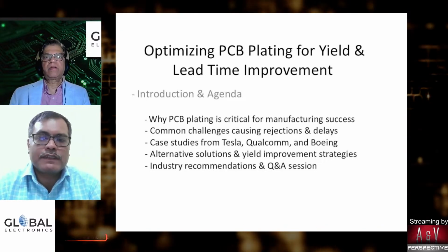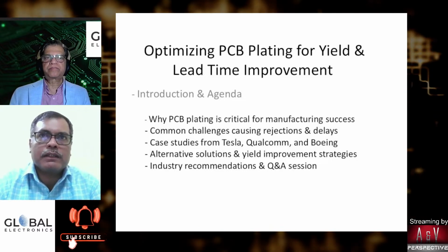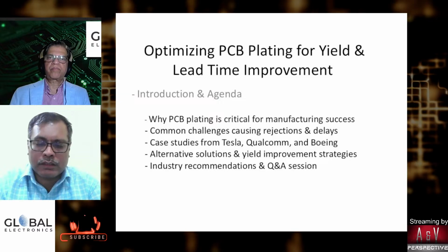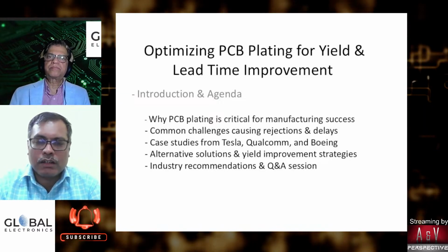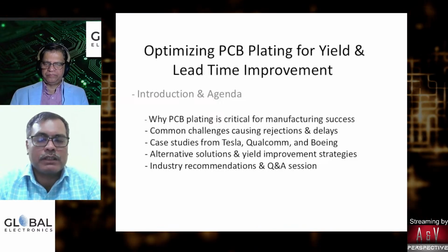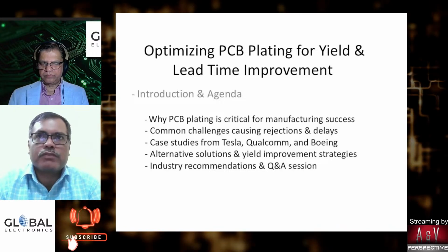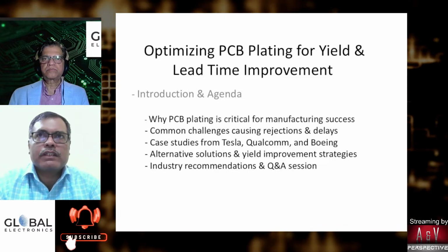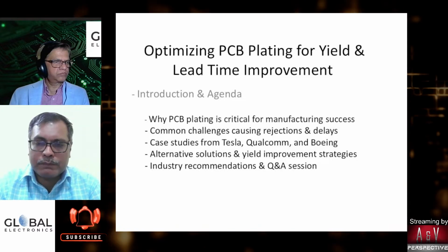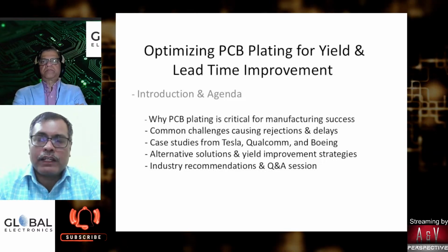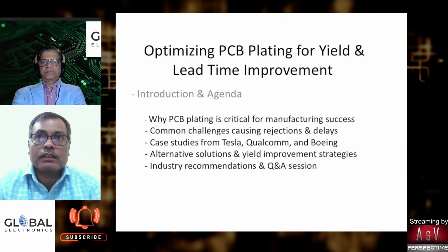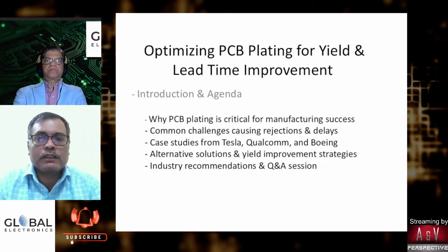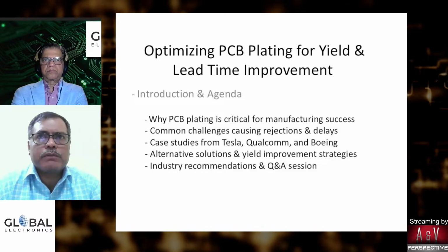If the Gerber is given, Gerber means the PCB technology: everything is there, your drill files, layout and all other technology parts put together is called Gerber. When we share that Gerber with the PCB manufacturer, their capabilities come into the picture. That is very important, like minimum spacing, minimum line width, minimum drill dia, high density interconnect HDI PCBs, and micro vias. That plays a very important role in selecting a PCB manufacturer.